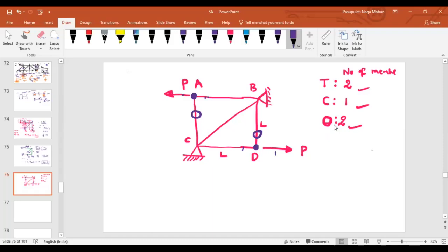No. Now, how can I balance these forces here? We can apply our classical knowledge. First of all, what type of force is member AB carrying? Is it carrying tensile force or compression force? Tensile, sir. This is the tensile force, right? Yes, sir. What about this? Tensile, AC also tensile.